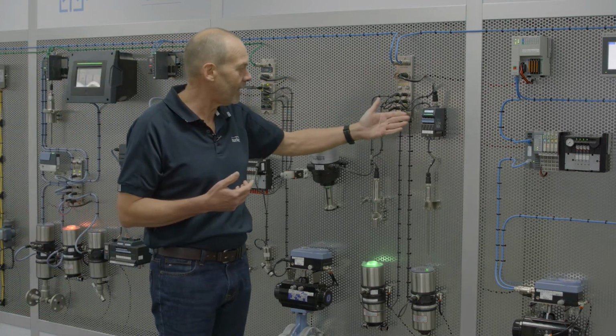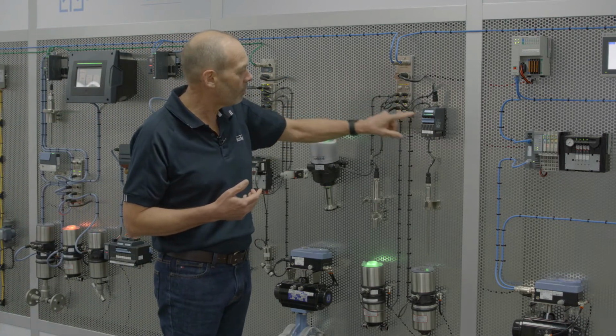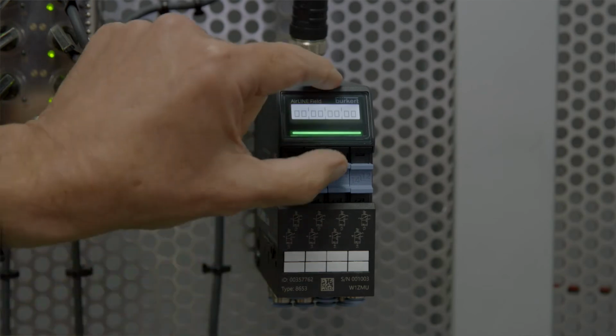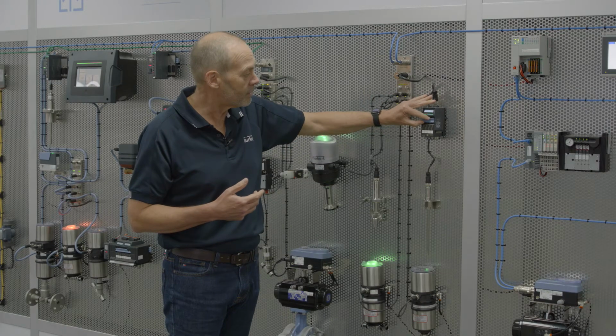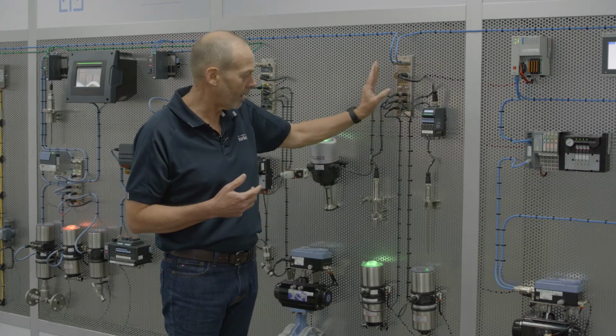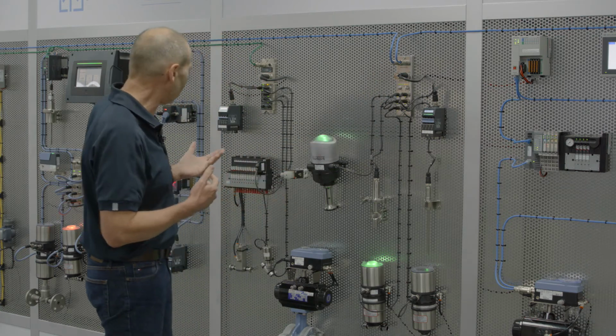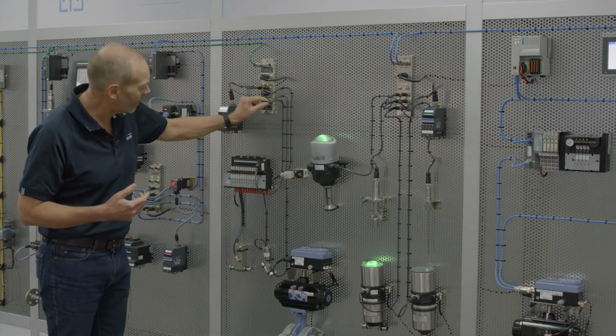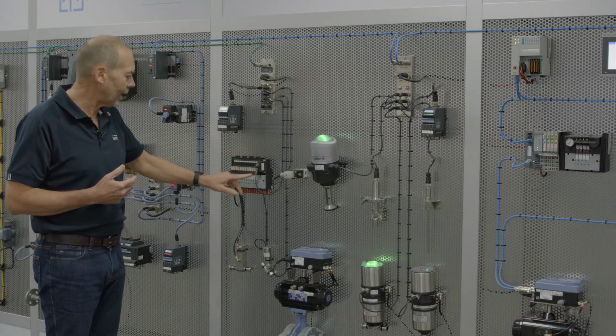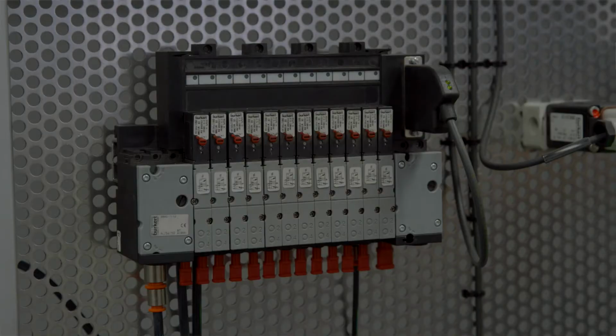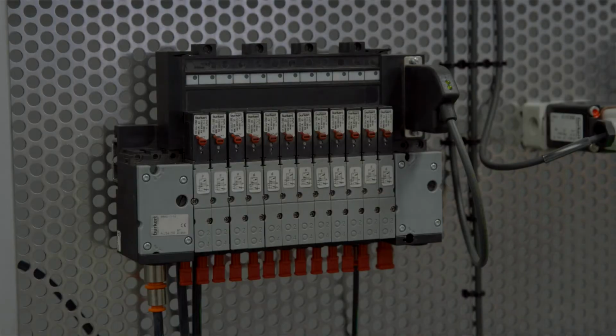Alternatively, over here we have a block talking to 8 valves in the field. These valves are all controlled via the IO-Link block. And on that same type of network port, in this example, we have up to 24 valves connected on a single IO-Link port.